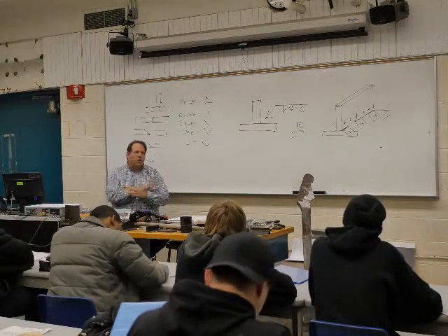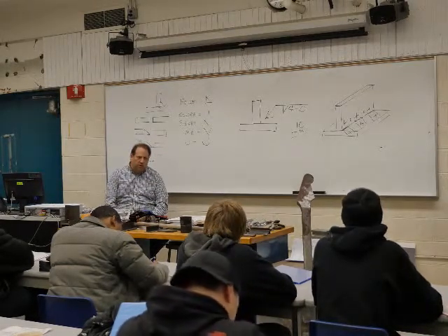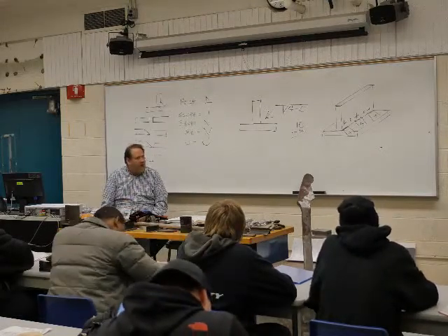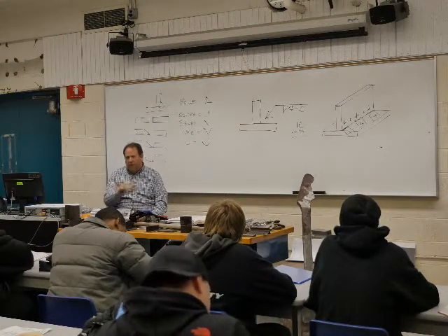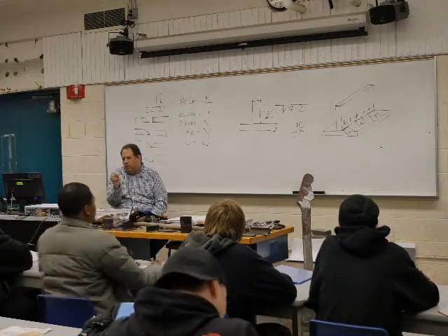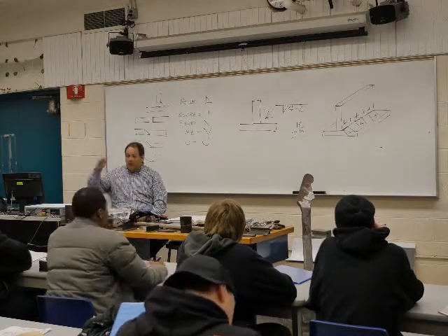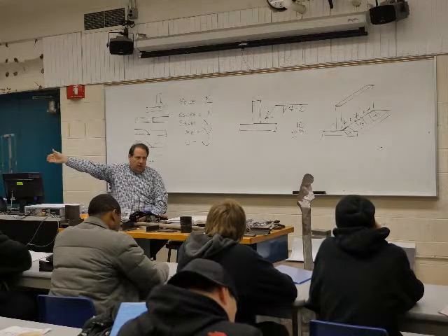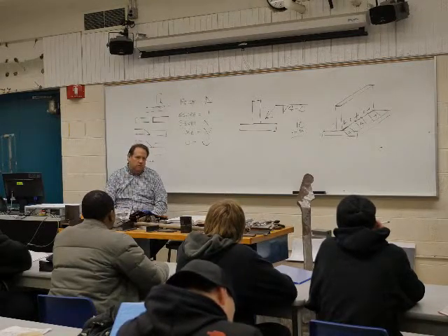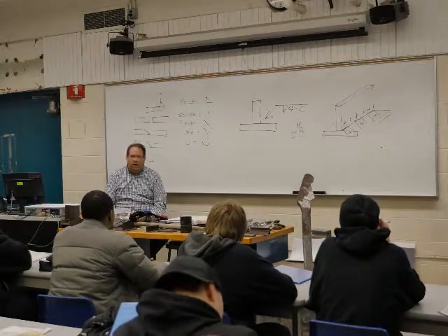Here's the thing. If we got a really long piece, let's say this thing is 8 feet long, but 4-inch stitch welds. If that dimension of 10 was really just the gap, or they gave you 6 as the gap, if you're slightly off on the start of your next one, and then slightly off again on the start of the next one, it will be an extreme amount at the end of that 8 feet. But if we're doing center-to-center dimensions, you'll be in more tight tolerance. So that's why they do it that way. It's just a closer tolerance to be able to measure that out, okay?